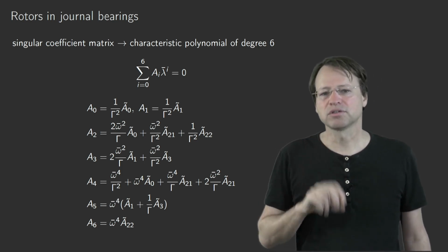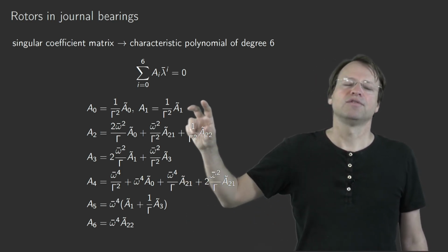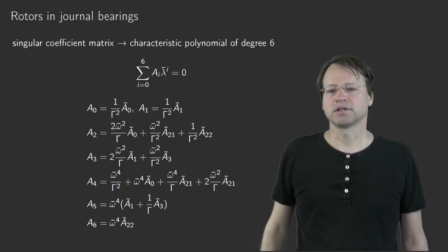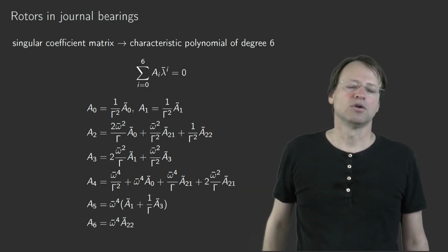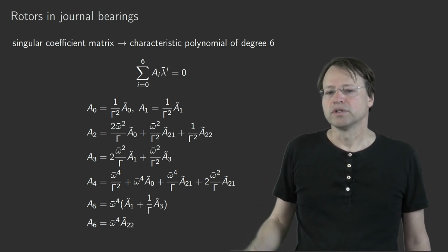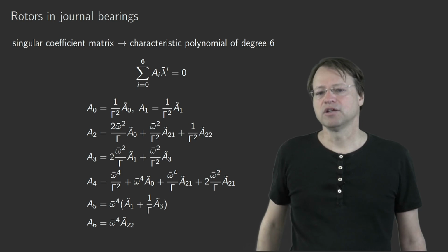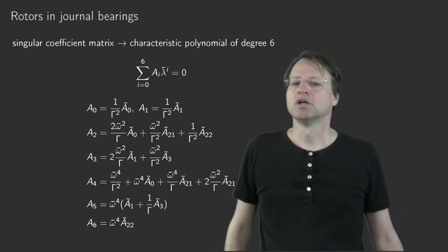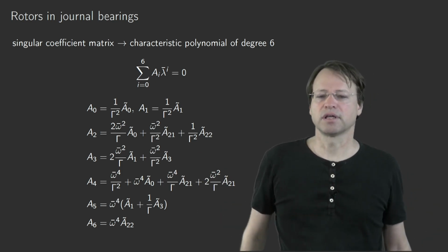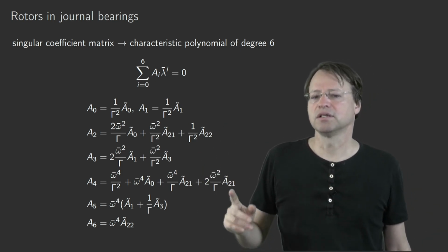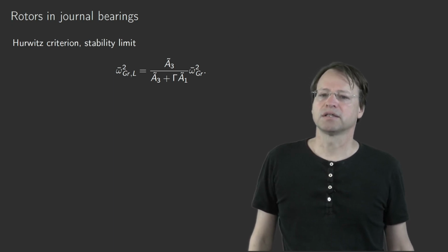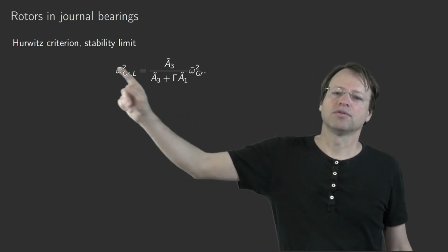If there are parameters you focus on, then if you do such a stability analysis with the coefficients of the characteristic polynomial and you want to apply the Hurwitz criterion, then it's a good thing to single out the influence by factors of these parameters you are interested in, and to lump together everything else. So everything else is hidden in these parameters A. So what can be said after application of the Hurwitz criterion?